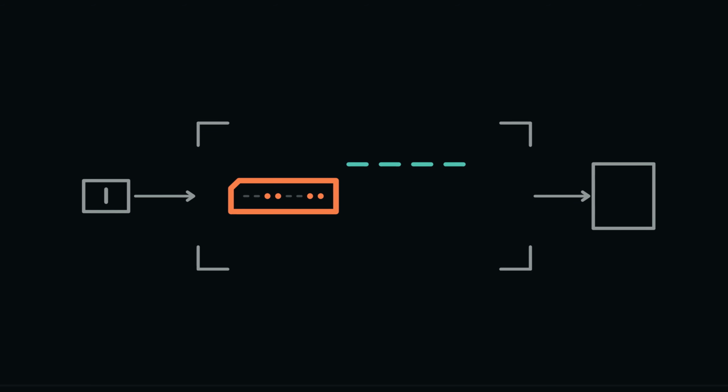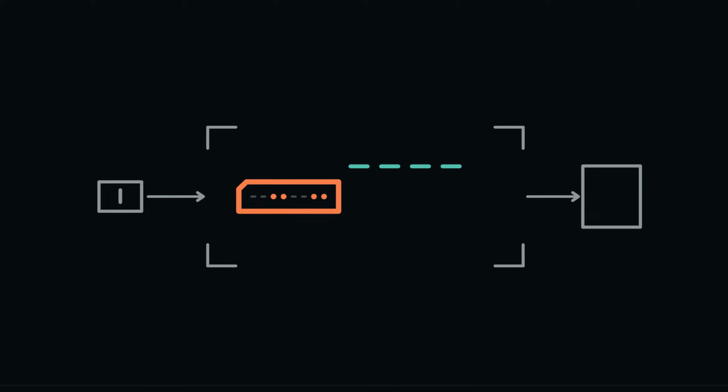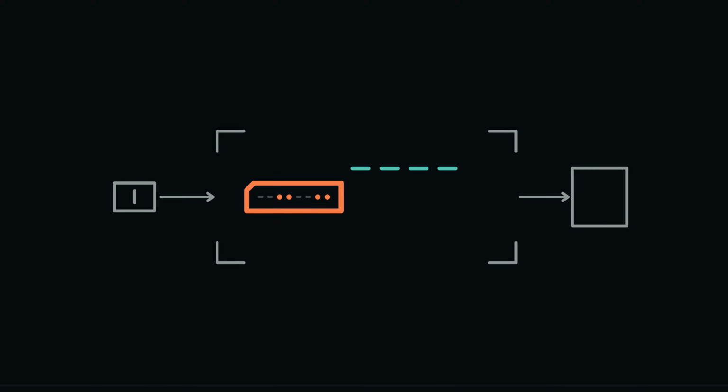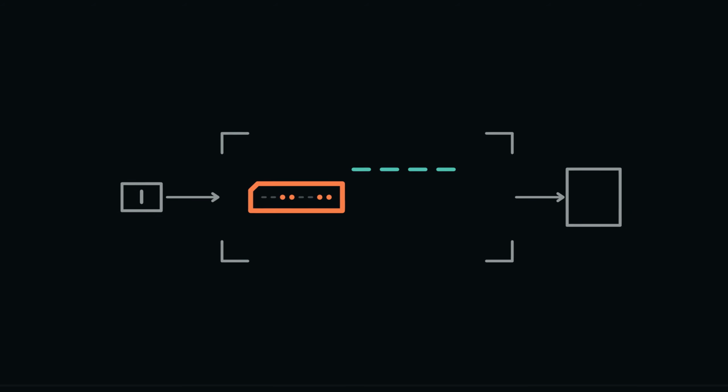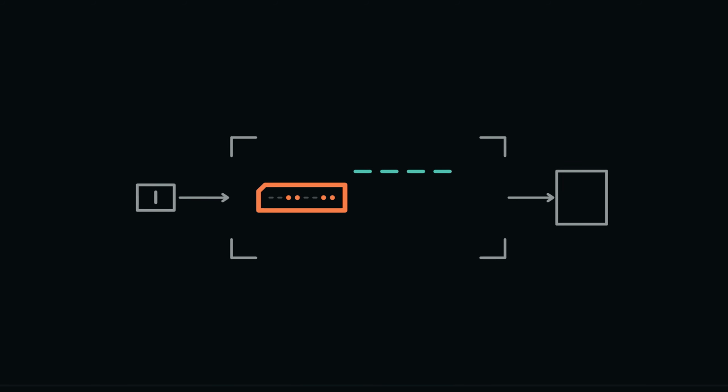Our byte now has a value and an interpretation, but it still sits in one register. If every source had a private 8-wire path to every destination, each new component would multiply the wiring. Keep the learned registers in their fixed positions, while one shared 8-line route grows between them. This route is a data bus. The name describes a shared connection, not a vehicle. A bus does not pick up a byte, remember it, and drive away. Circuitry at the endpoints changes electrical conditions on shared lines, and other circuitry may classify those conditions as an 8-bit value.